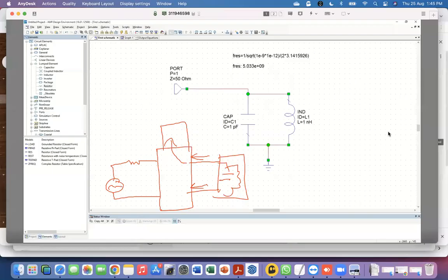It allows you to separate the waves going in two different directions. So in one direction it will go, and for the forward going wave, because it is generating the signal, it knows what that magnitude is. The reflected signal it is able to divert into a different direction, and there you have put a different sensor which measures it. So that's how you are able to measure the reflected wave separate from the incident wave.